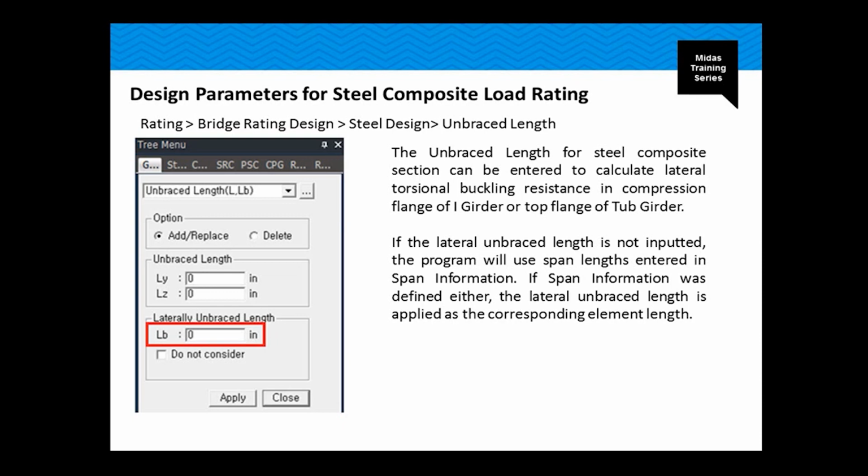If the lateral brace length is not inputted, the program will use the span length, entering the span information. There is a span information that you can also apply in the program, and the program is going to use that as a reference for the brace length. If the span information was not defined, the lateral brace length is applied to the corresponding element length.